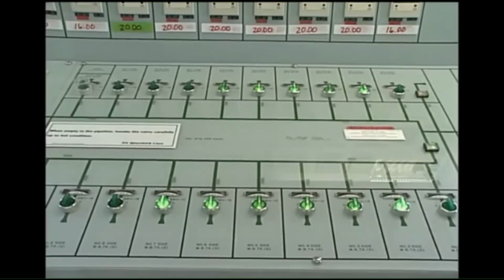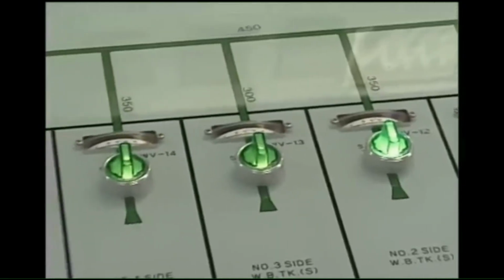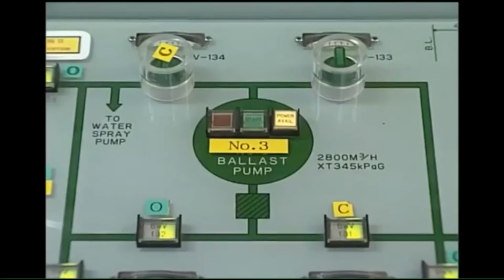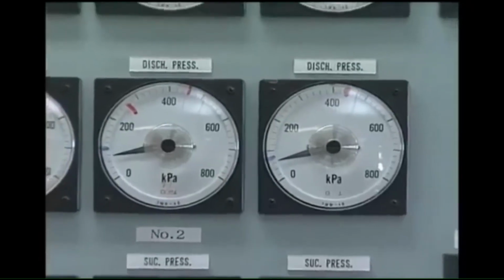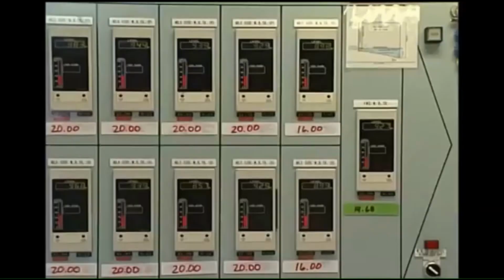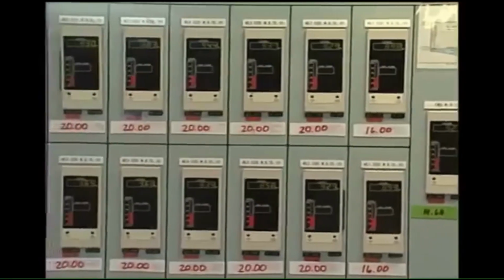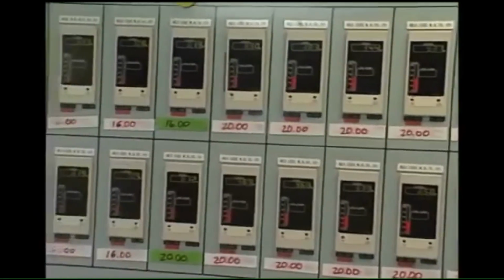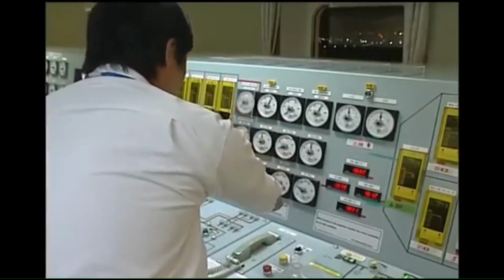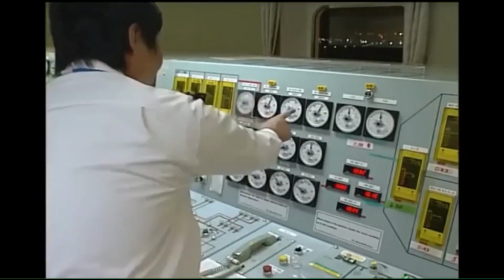To begin with, set all valves at appropriate openings. While in operation, only operate the valves to be used. To avoid wrong valve operation, secure a cap on each of the valves not in use. When opening or closing valves, make sure to pay attention to the pertinent pressure gauges. Also check the pertinent level gauges from time to time. When carrying out any task, never fail to answer back, check, execute, and report.